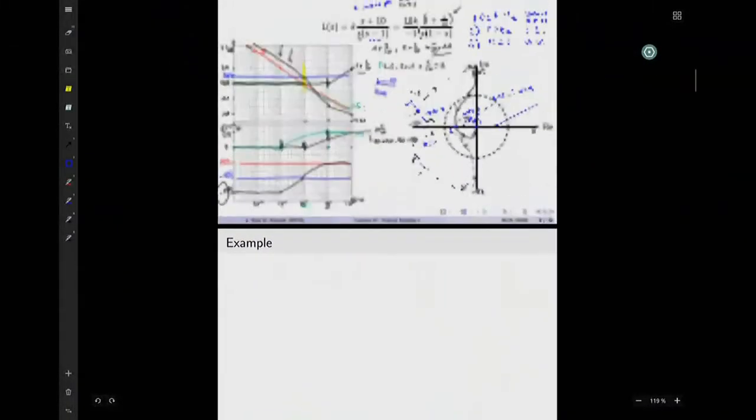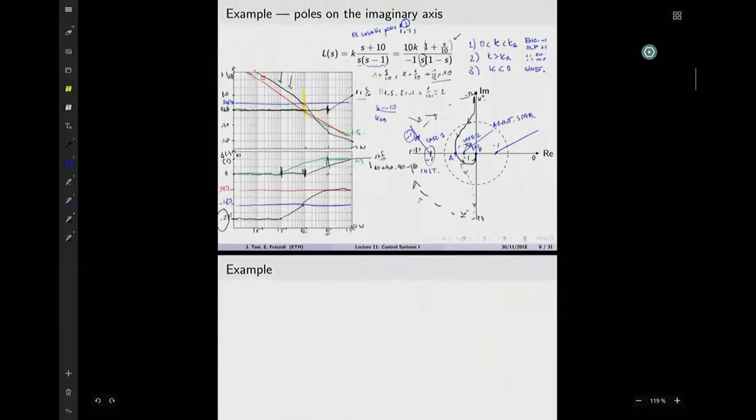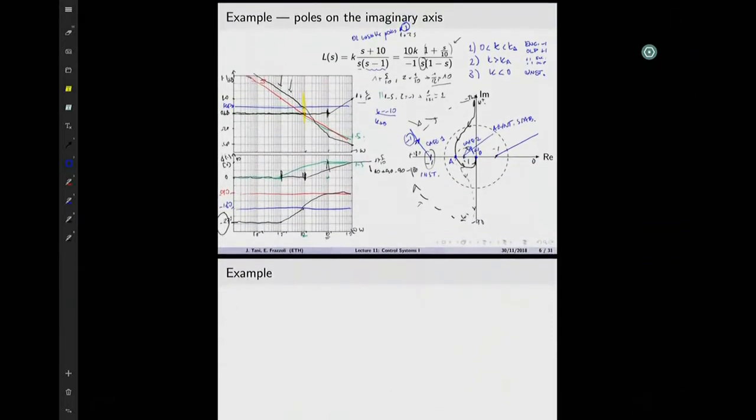one thing we could do is say, hey, we have introduced an algebraic way to see when the roots of a polynomial change sign. In this case, what we care about, instability, stability, whatever it is, really means that the real part of the poles of the closed loop transfer function is flipping sign.